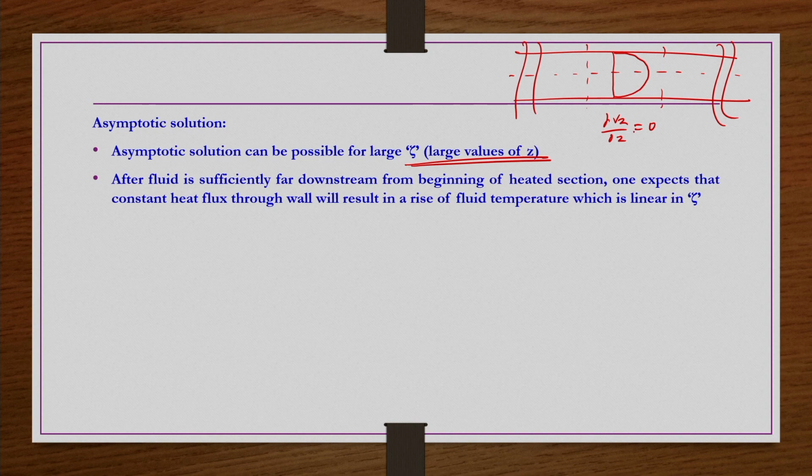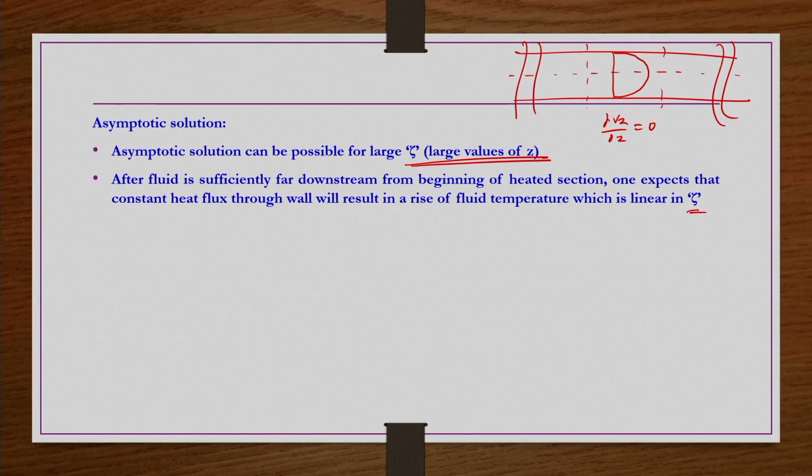So, then obviously that velocity is not going to affect much the temperature profile here in the fully developed region, and in which direction will it not affect? It will not affect much in the z direction. The convection whatever is there, the velocity profile is not going to affect the heat transfer because of the convection much. So, only whatever the variations are there in the z direction, they are expected to be linear. Okay.